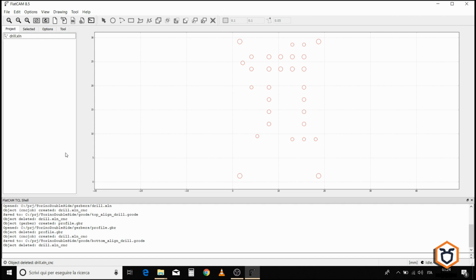If you have smaller holes diameter with respect to the through-hole components diameters, we suggest you generate more than one Gcode file for the drill, predicting a tool change for every different drill machining. In our case, since the diameters are quite similar, since the vias are quite big in this example, we may use a unique drill bit for every hole. In this case, we will choose a drill bit with 0.8 mm of diameter.